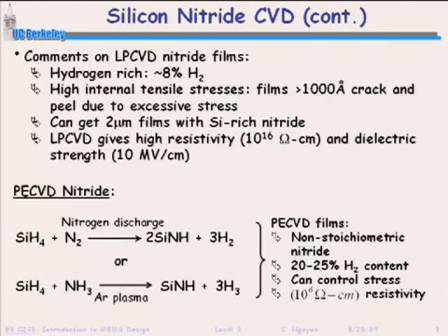If you don't deposit silicon-rich, you end up having cracks in your films, and they start peeling from your wafer surface when they're greater than 100 nanometers. You can really get to about 300 nanometers, and at 300 nanometers, that's pretty much it. Things are going to peel off of that wafer just because of the high stress. Why do things peel off of wafers because of high stress?